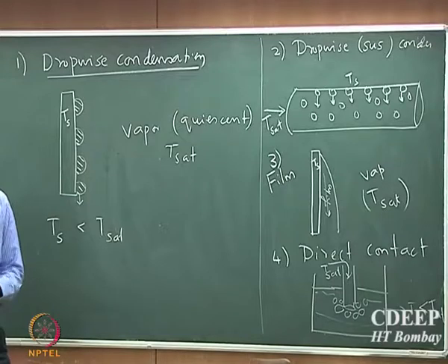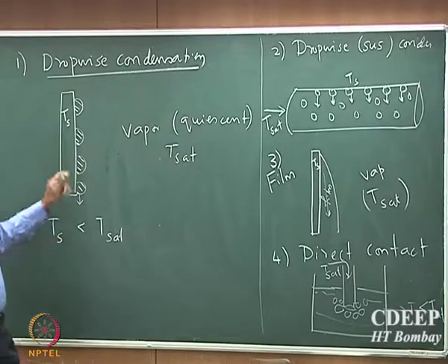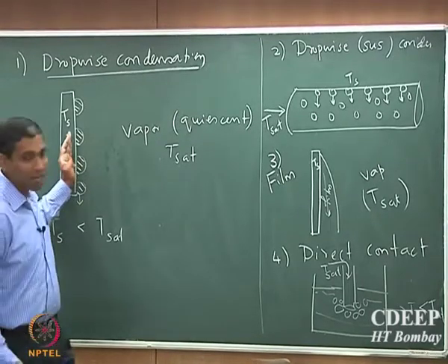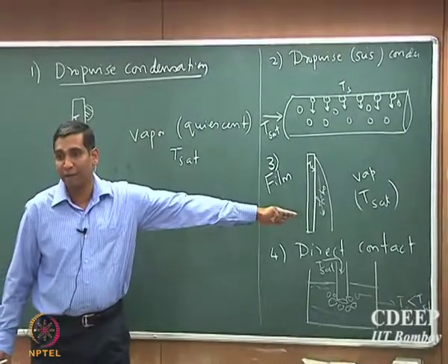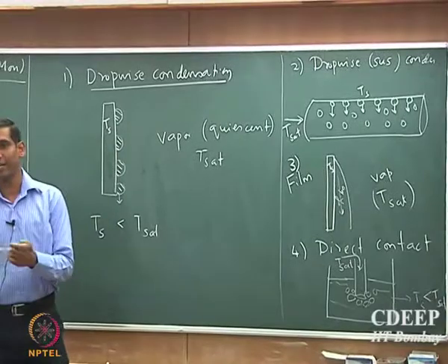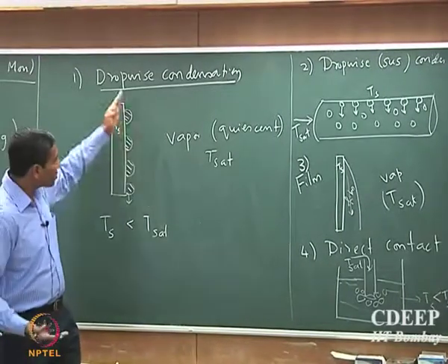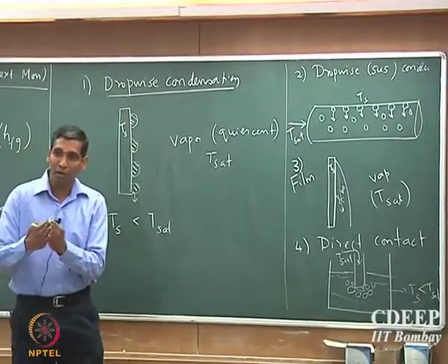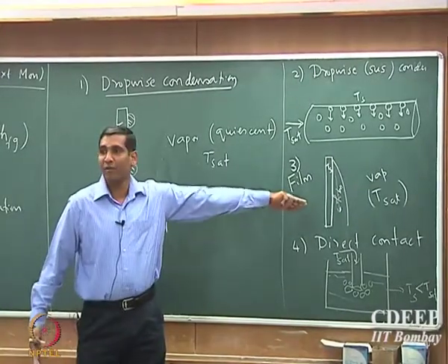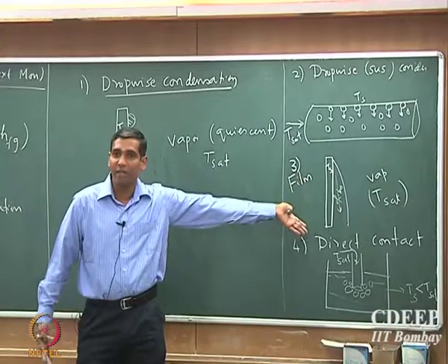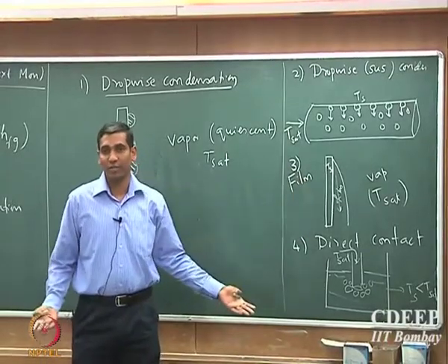If the condensation rate is significantly higher, you will start with dropwise, and then it will transition to film. Because the condensation rate is significantly higher, before the drops fall, more liquid will come and deposit on the surface, and so you will have a continuous flowing stream of liquid, which is actually a film condensation process. Okay.